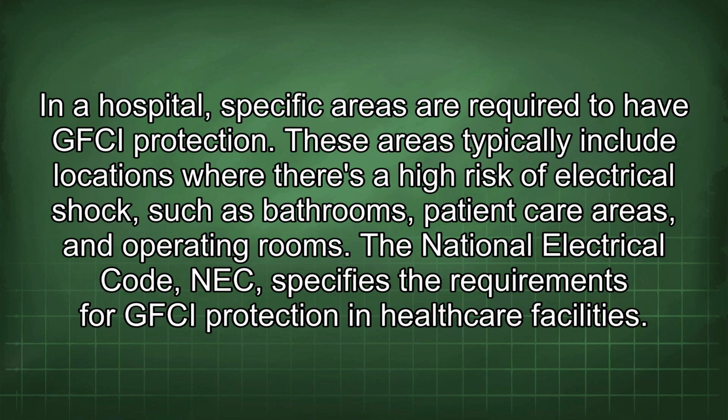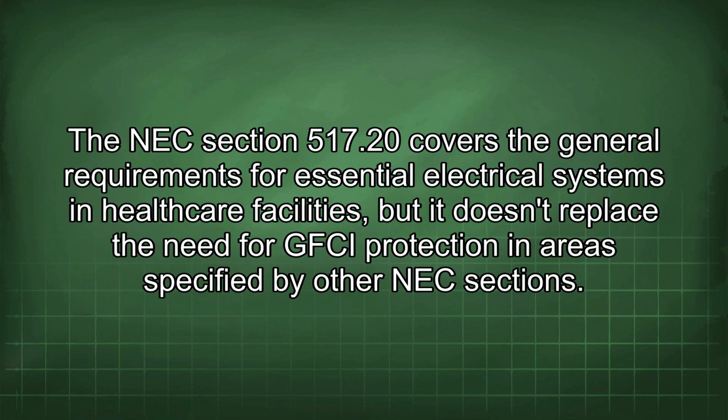These areas typically include locations where there's a high risk of electrical shock, such as bathrooms, patient care areas, and operating rooms. The National Electrical Code (NEC) specifies the requirements for GFCI protection in healthcare facilities. NEC Section 517.20 covers the general requirements for essential electrical systems in healthcare facilities, but it doesn't replace the need for GFCI protection in areas specified by other NEC sections.